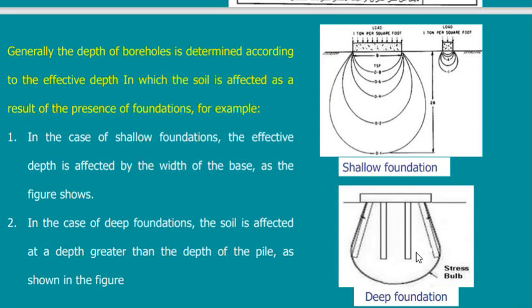In this case, I need my borehole to cover the length of the deep foundation plus another 5 meters at least. So my borehole should reach this depth.